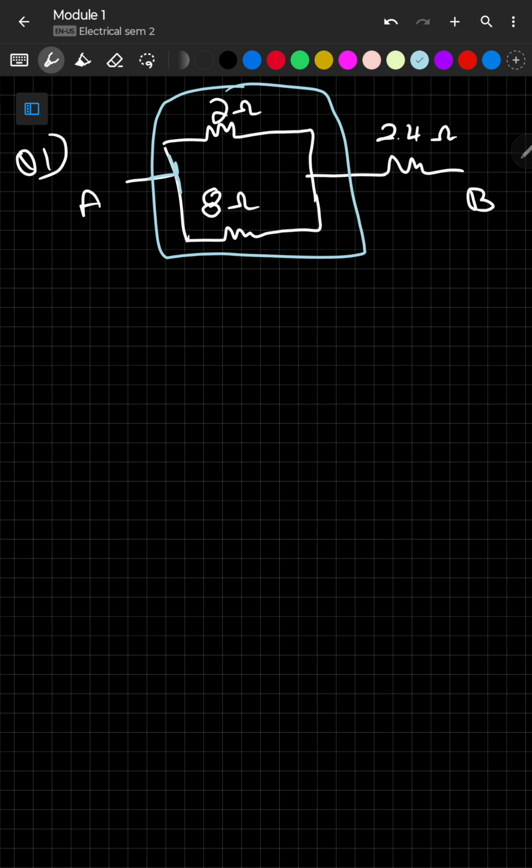I will explain so in the beginning. Afterwards, you can get up the momentum. It's branching here, so we know it's parallel. So we have to find the R equivalent, obviously, right? So R equivalent equals to 2 into 8 by 2 plus 8. You can write the formulas first and all of that you can do. Here I'm just doing a little bit directly. 8 to 16, so that will be 1.6.